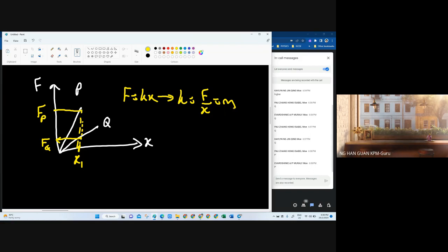So be careful about the two different kinds of diameter. Last week one teacher asked in the group to explain the difference between the diameter of the wire and the diameter of the spring. So the teachers were confused with the terms of diameter. When we talk about the diameter of wire, we're talking about the thickness of the wire used to make the spring. We're talking about the diameter of the spring coil. When we use the wire to make the spring, the spring has a diameter, it's a coil diameter. So these two diameters will result in different effects.